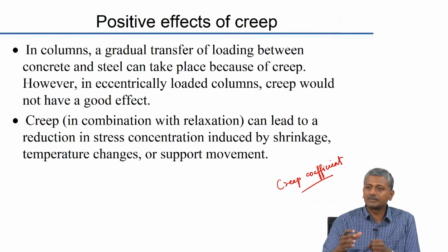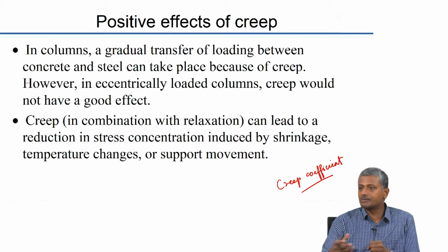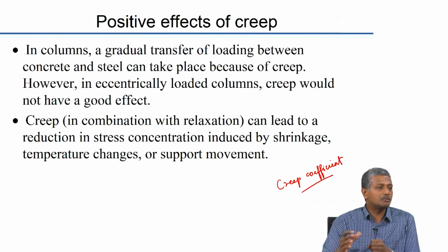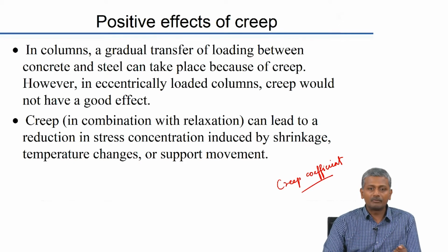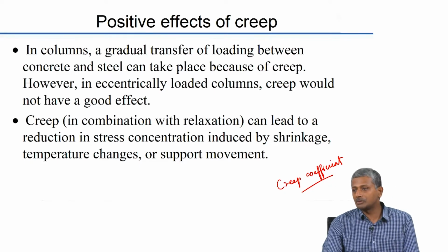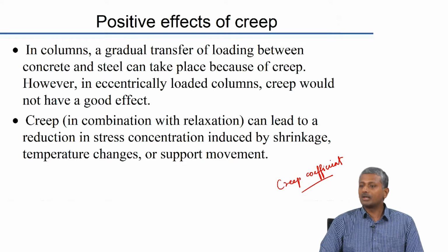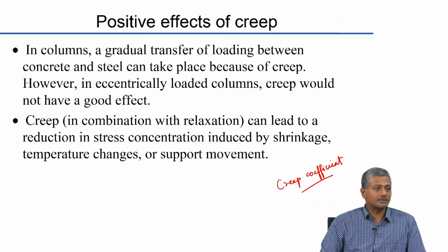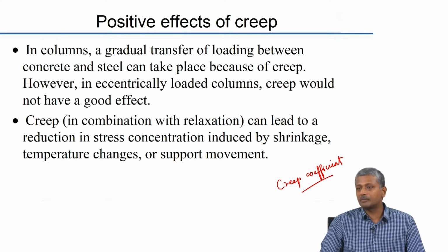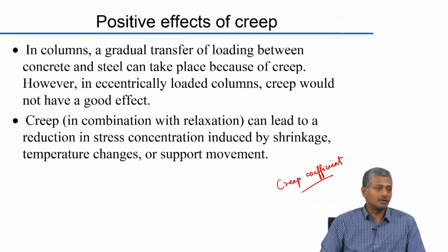So, there is always a need for additional research to understand how the creep coefficient is altered when we change the design of the concrete significantly, especially with our new philosophy of the particle packing approach. There can be a lot of changes to the creep coefficient, and we have to be more realistic in terms of the design when we incorporate creep coefficient, because that input can actually change the kind of parameters that we get for design significantly.